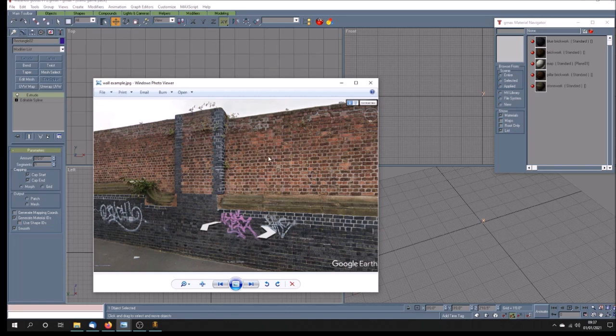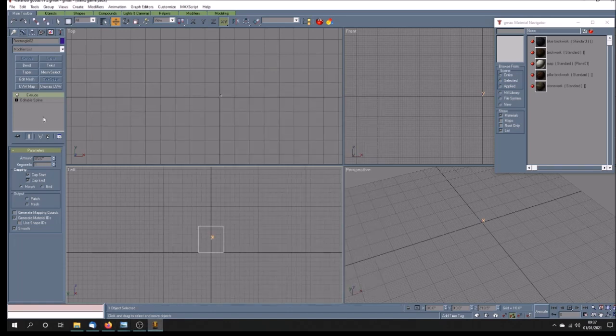Bricks were about 4.5 inches deep at this time when this was made. So they're about 9 by 2 3/4, and then about 4.5. So I'm going to say that that's 1 foot deep there. So this, I think, is about 1'8", from the back of this wall to the front of this bit here. Okay, so going back into this, I'm going to extrude it 1'8".